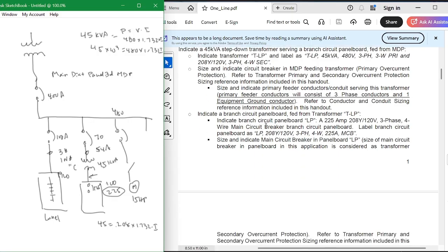Okay, so 15 is about 15, what? It's 480 times... okay, so it's about 15 amps. All right, so you can have about 15 amps going through here. The amps is usually about the same size as the horsepower at 480 volts. So that's about right. Now he sized it with a 40 amp main, and you can use that 40 amp in the sizing of the wires accordingly.